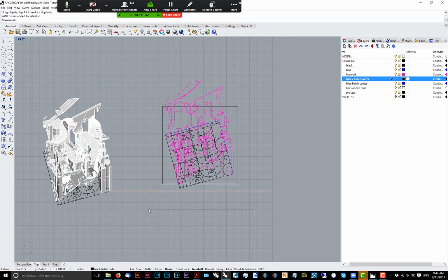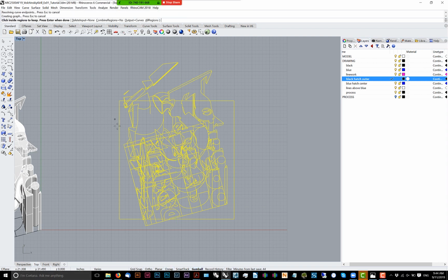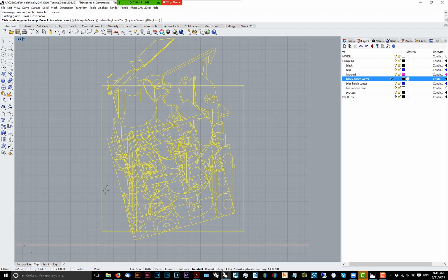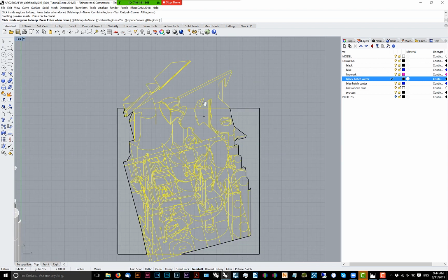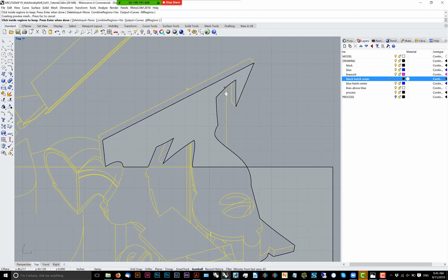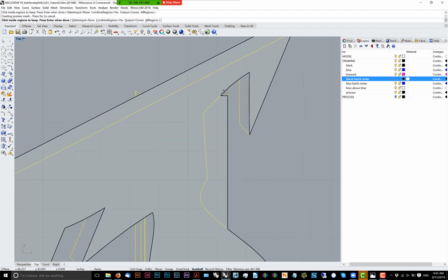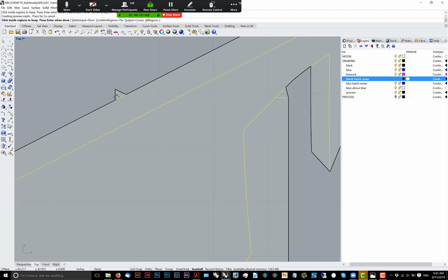And then we will actually use the curve boolean command, so that's curve boolean in one command, to then start to color. So we'll color these two sides and also any kind of geometry that flies out of our artificial boundary that we created.